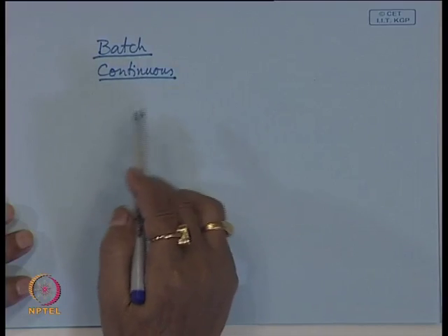So, the total quantity of polymer manufactured per day will be less, whereas in a continuous process, if these monomers are continuously fed to the reactor on one side, and from the other side the product is collected, then there will be higher productivity. But the problem is, in a continuous process one cannot go to higher conversion. You can get a high molecular weight product, but the conversion may be 20%, 30%, because there are problems like viscosity and other things, handling of this entire mass.